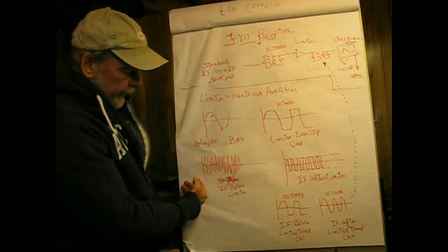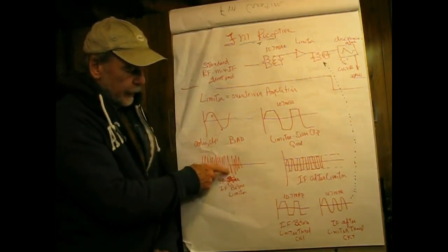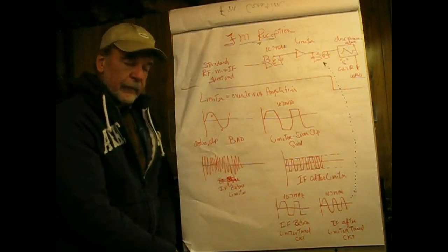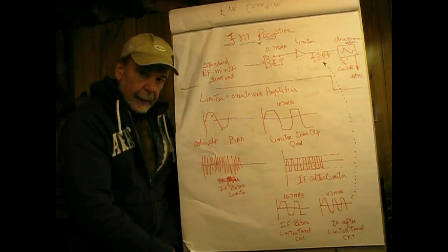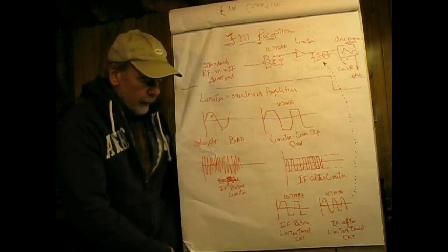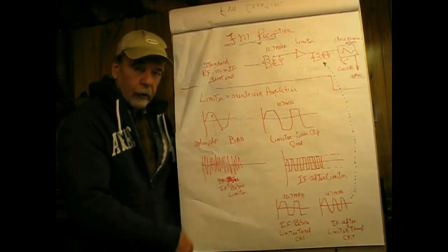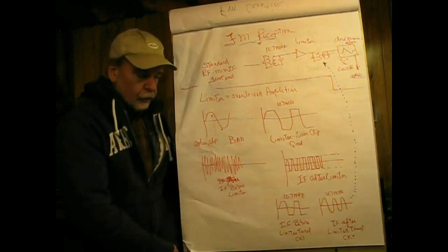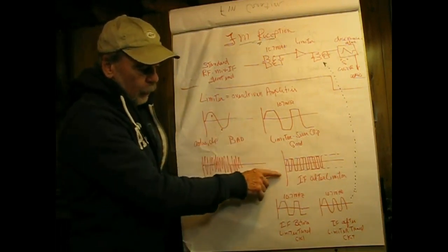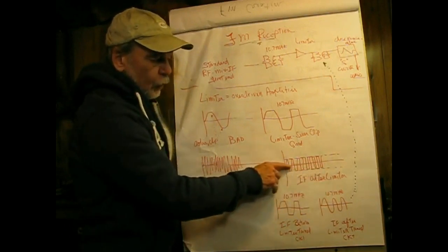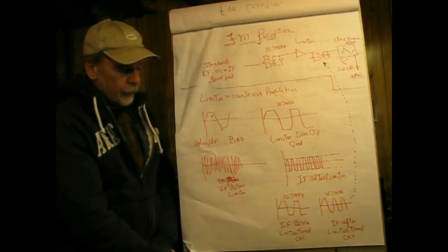So here I've got an incoming intermediate frequency signal, and it's designed to show you that there are all kinds of variations in amplitude. Part of that is due to incidental AM, which is part of the FM process, and the rest of it has to do with, say, lightning, flicking on and off light switches, car ignition, and so forth. This is fed into a limiter which severely clips it, and the output looks like a squarish waveform, basically the same amplitude.